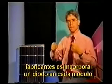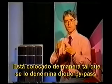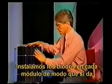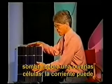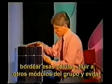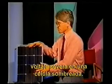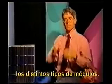We take the responsibility of building into each one of our modules an electronic device, a diode. We call it a bypass diode because it allows current to bypass around a shaded cell. We install the diodes in each module such that if there is shading on any one cell or a group of cells, the current can be bypassed around those cells, flow on to other modules in the group, and avoid the extreme negative effects of severe voltage drop in a shaded cell. Let's take a look at how we actually wire in bypass diodes in our different types of modules.